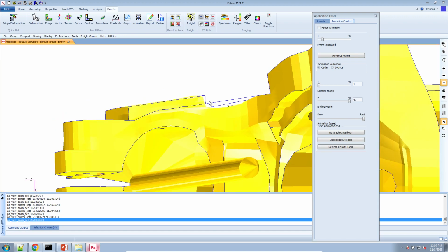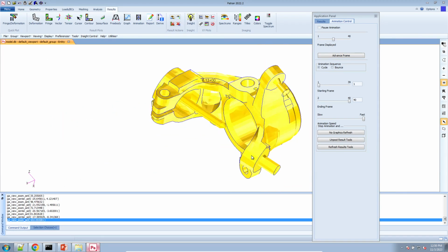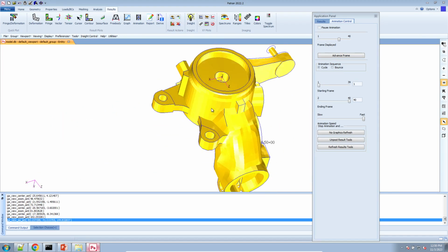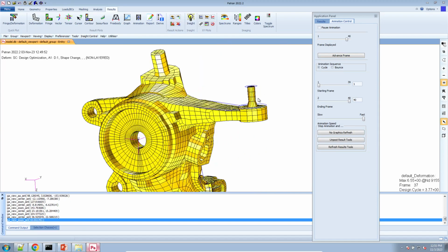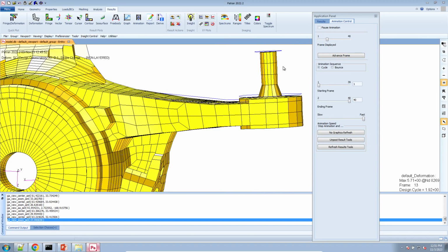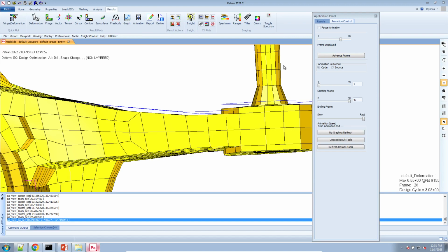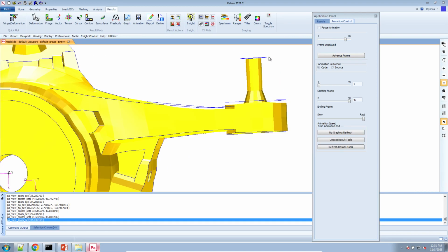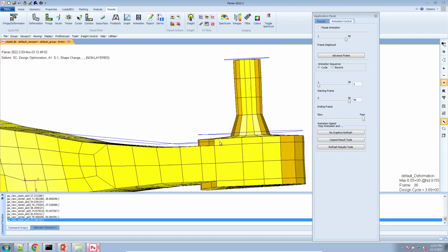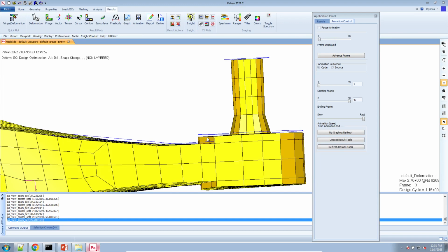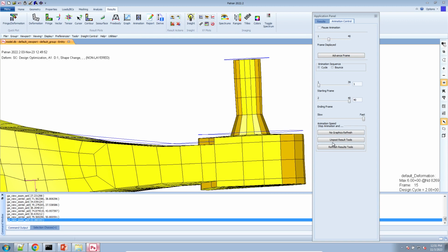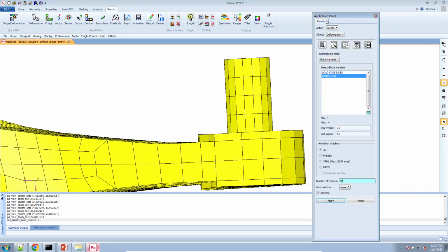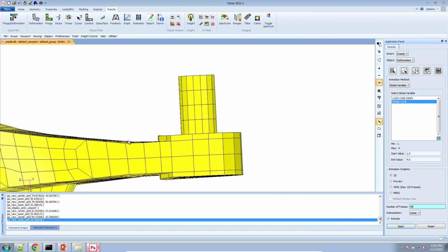Now, the same can be said for this other region where we change the shape. So let's go ahead and look at this. Here we were able to actually contract these 2 shapes to minimize the mass in this region while making sure the stress is within our specified bound. Now, what is there left to do? We need to make sure that the stress value is under the upper bound of 40. So how do we do that?